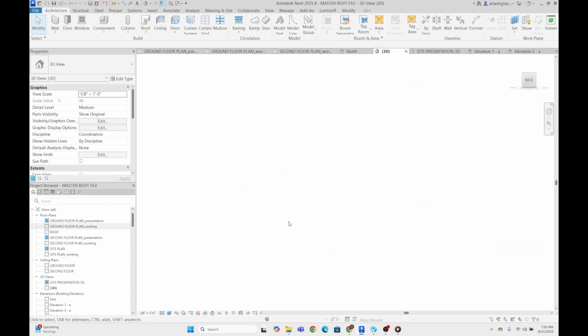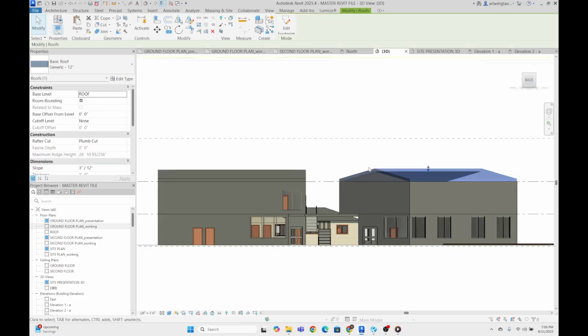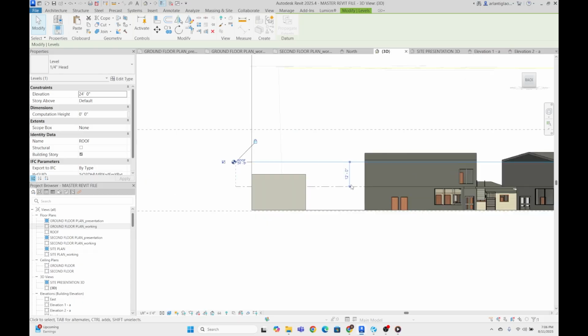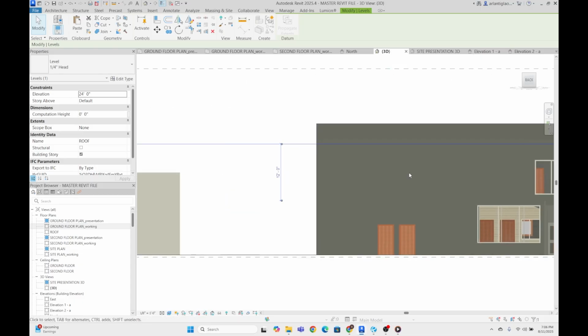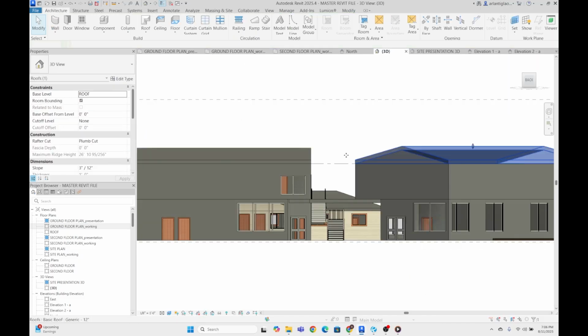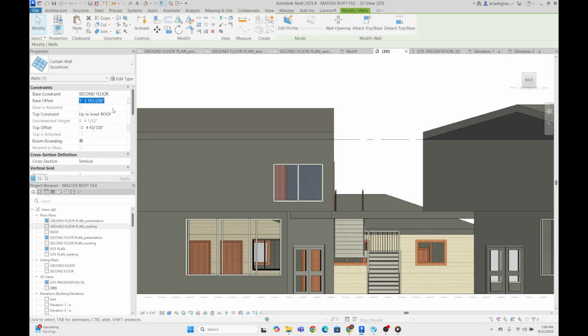Right now it's looking like I want to extend the slope of this roof. And maybe even change up the level so it's a little bit shorter, because 12 feet is actually kind of large from what I see. So I'll change that to 10 feet real quick. I'll adjust this to be like 3 feet from the base.